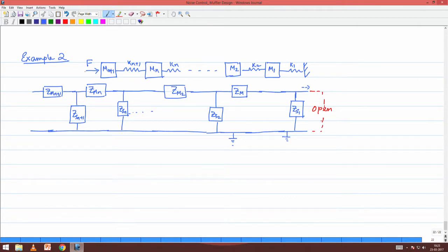and then finally this mass is seeing a force which is capital F. Force is analogous to voltage in the electric circuit theory, which means the input point of the mass will see a voltage which is F. So, the circuit is fairly easy to draw. No matter how many springs and masses you give me, all that I need to do is keep arranging the springs in the shunt position and the masses in the inline position and complete this circuit.